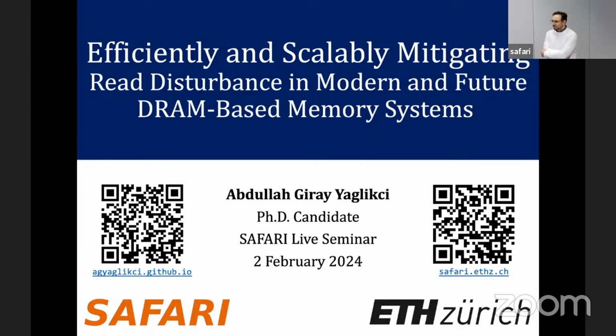If the microarchitecture level has information about both, why not implement only that? Why do you need the other layers? So far, what we did was implement things in the memory controller. But in BlockHammer, for example, we had the challenge that we didn't have the information about the row address scrambling inside the DRAM chip. So that was one example.